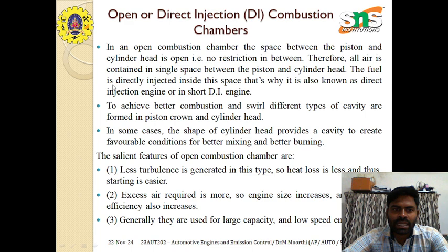So the fuel is directly injected inside this space. That's why it is known as a direct injection engine, or DI engine. To achieve better combustion and swirl, different types of cavity are formed in the piston crown and cylinder head. If you are going to mix air and fuel properly, you should have proper swirl, so that the air and fuel are mixed in the proper ratio.